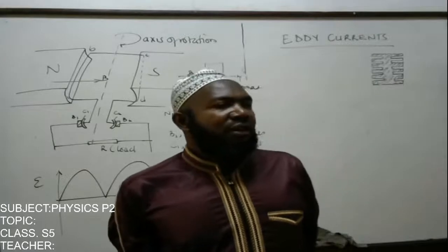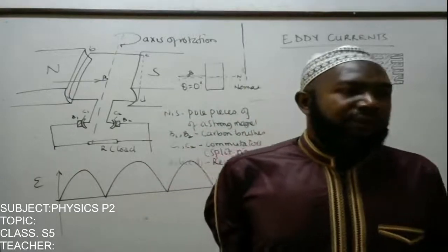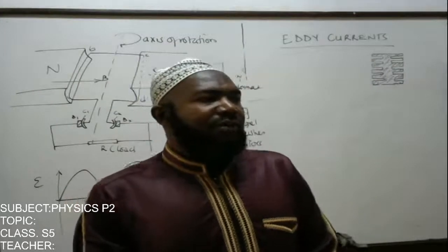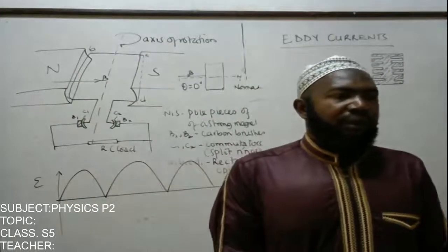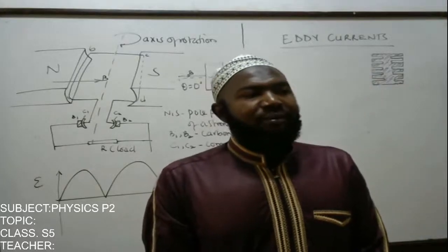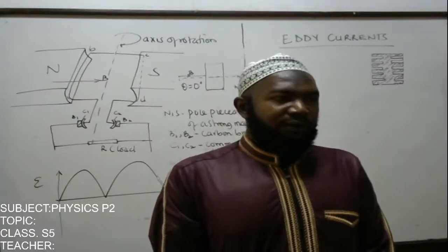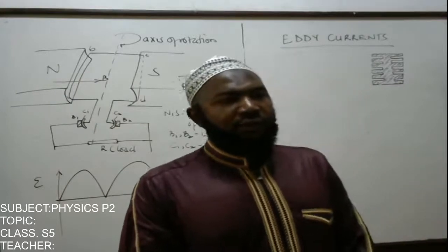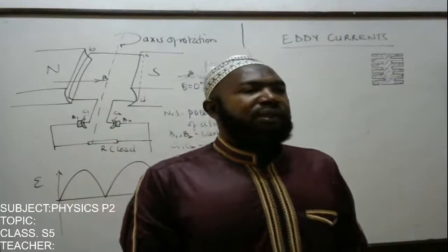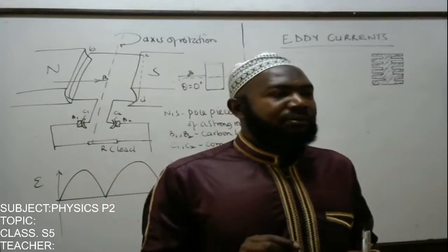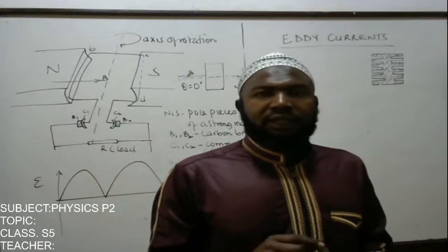So we are saying the coil of the pointer is wound on a metal frame. When the coil is made to rotate in a radial magnetic field, of course the flux linking it changes, and EMF is induced and consequently eddy currents flow. So a large eddy current is induced in opposition to the rotation of the pointer. This makes the pointer attain equilibrium position without oscillating many times per second.